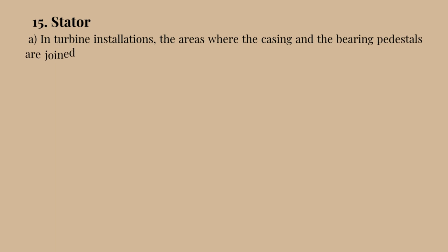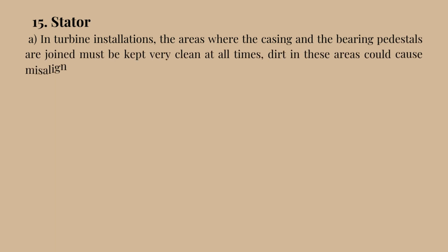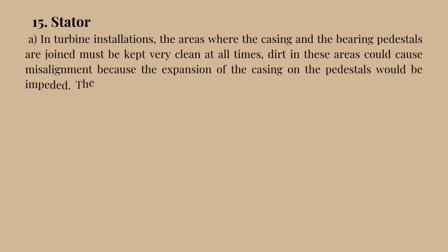15. Stator. A. In turbine installations, the areas where the casing and the bearing pedestals are joined must be kept very clean at all times. Dirt in these areas could cause misalignment because the expansion of the casing on the pedestals would be impeded.